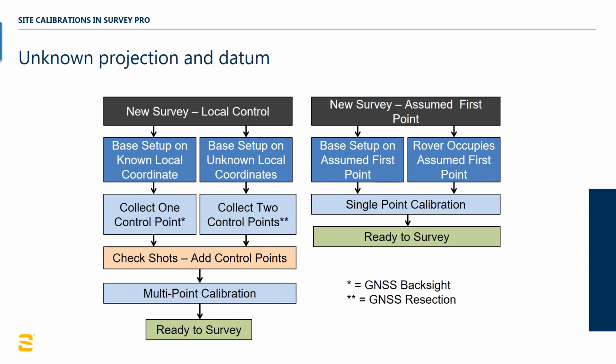And when that happens, if you look through the raw data view, you will actually see a warning that tells you that what was reported as the as-built location when you staked it is now different from the current location. But for all cut sheets and all reporting of what the stakeout delta was, that is locked in and hard-coded at the time that you store the stakeout point.